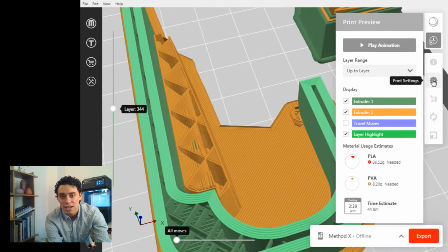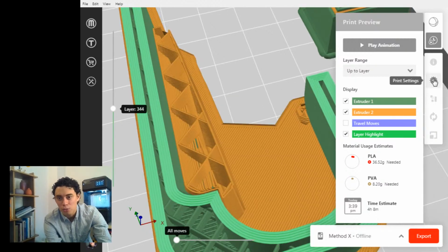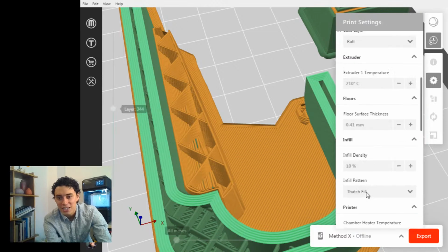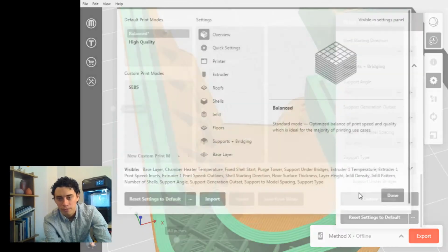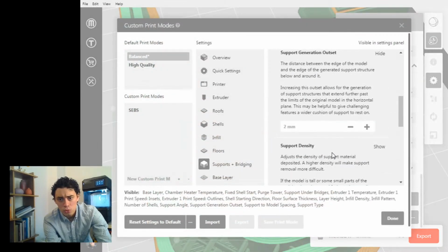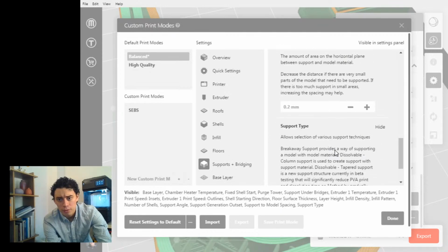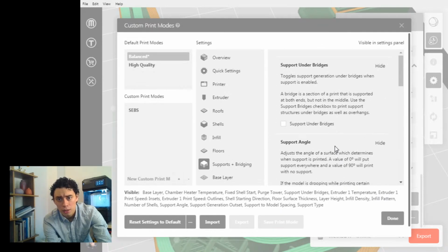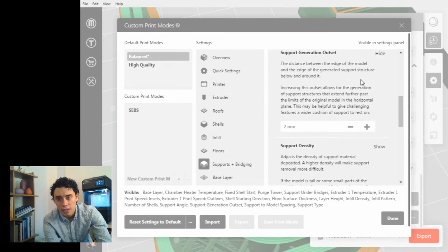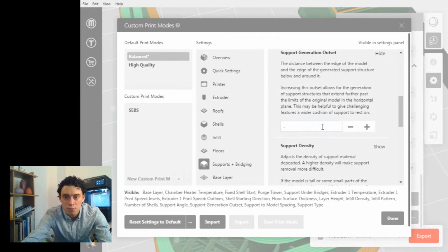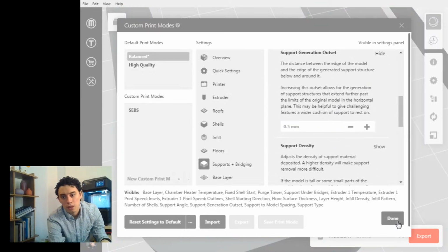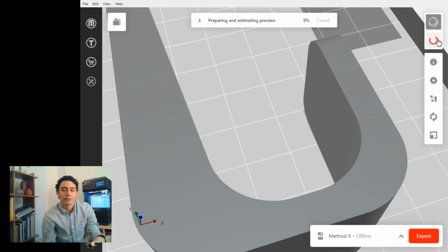And if I change that again, I'm sorry, but keep this dimension in mind. It's about the same as a wall thickness right here. So if I change that back to, where is it? Under angle outset. Okay, so the standard, which is 0.5 millimeters, done. Slice again, and you will see how much closer it gets.